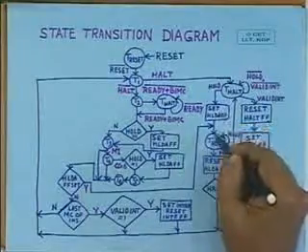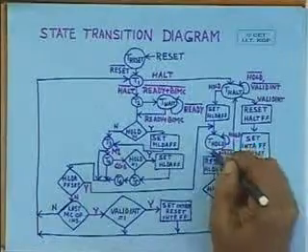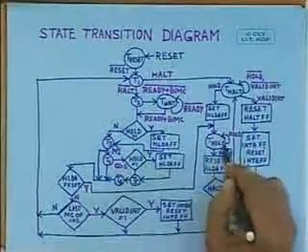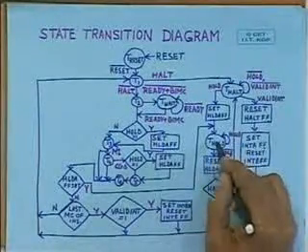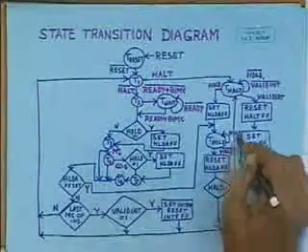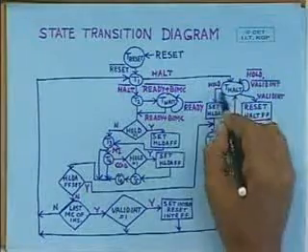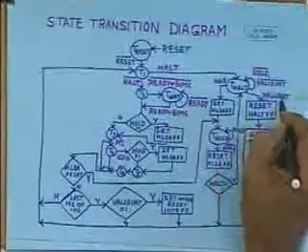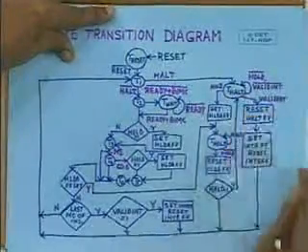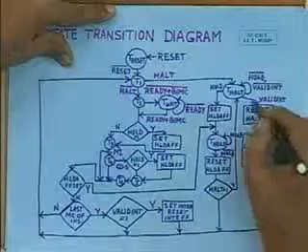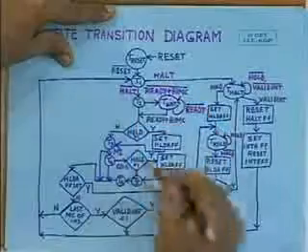After performing the data transfer in DMA mode, as it comes out of the hold, it returns back to the halt state. From the halt state it can come out only when there is a valid interrupt. As long as there is no valid interrupt, it remains in the halt state, and whenever there is a valid interrupt, it permanently comes out and starts executing the next instruction.